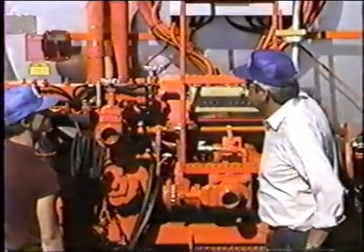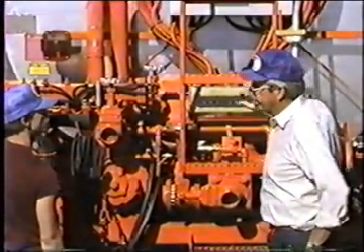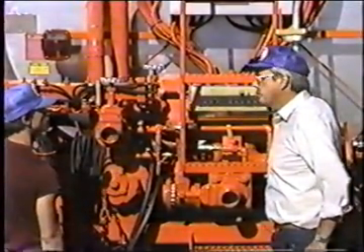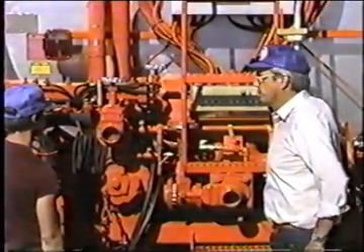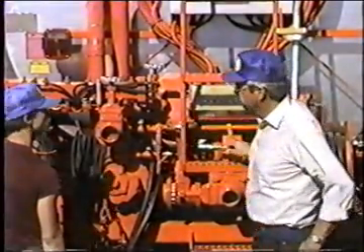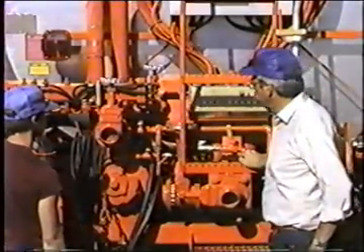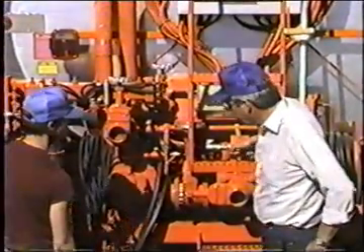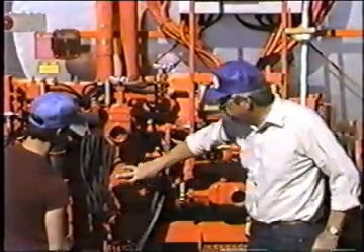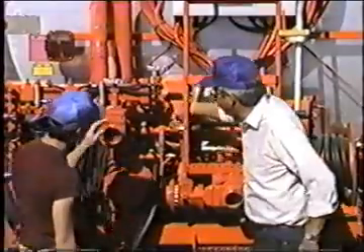On the computer unit, which this is, the computer does that. That is, when we tell it to circulate in the cab, it'll turn the pump to whatever speed we have pre-selected and told the computer to circulate at. This one is probably set at like 40 gallons a minute circulating speed. Okay, we're coming out of the bottom of the tank, in the bottom and out the top again, so that the pump is running forward. We're going into the spray bar valve.